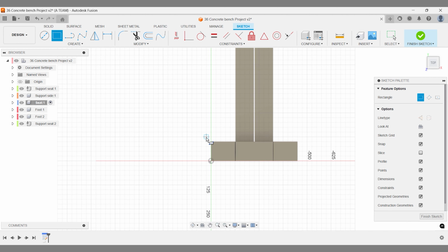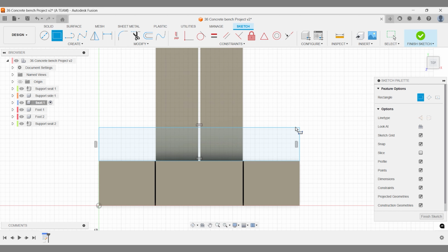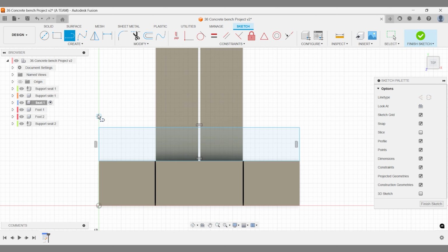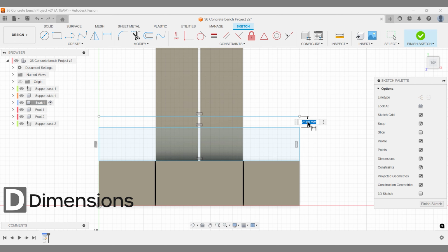You could use the project tool again, but the grid and current geometry make it easy to find the right spot. Make the part 75 mm wide. You can move the sketch 2.5 mm along the axis, but this gives you a chance to practice offset, trim and extend.